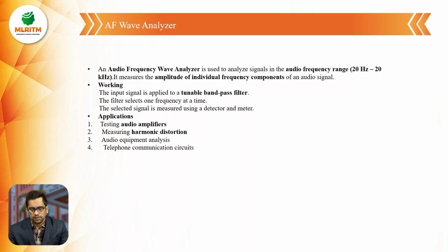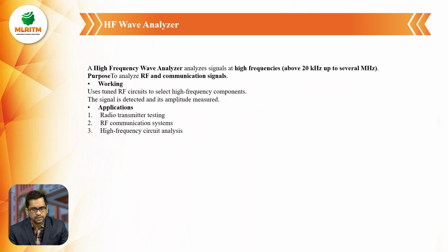What are the applications of these AF wave analyzers? The AF analyzers are mainly used in testing audio amplifiers, measurement of harmonic distortion in audio frequency applications, audio equipment analysis, and telephone communication circuits. These are the main applications of AF wave analyzers. Coming to the next type of analyzers, the HF wave analyzer. HF means high frequency, like 20 kHz up to several megahertz.